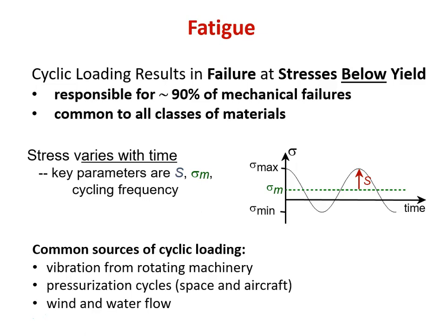design loads. So you can think about fatigue as working in tandem with what we've learned about fracture, and being a way that you're growing that A, the crack length, given a certain applied design stress, to the point where you then exceed K1C and you fail by catastrophic failure and spontaneous crack propagation. So there are some defined characteristics of fatigue that allow us to understand it and then basically design to preclude it. Something to, again, be cautious of.